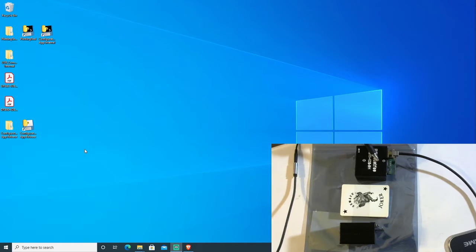One thing to note is pulling the jumper like that could be a very good analogy to an umbilical disconnect scenario. So if this does need to be embedded in a closed system for any kind of flight and put in low power mode, you could use the umbilical disconnect just like we did with the jumper to power up, and the unit can auto trigger itself as well, so it can run completely autonomously upon umbilical disconnect.